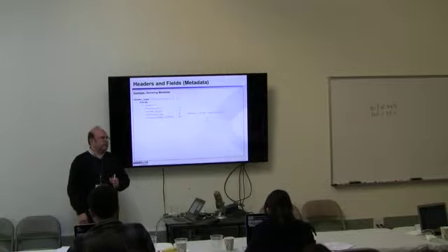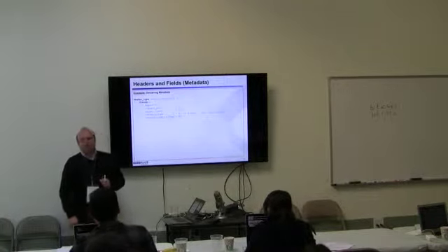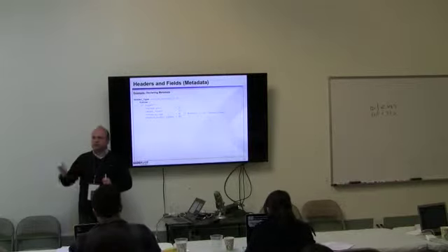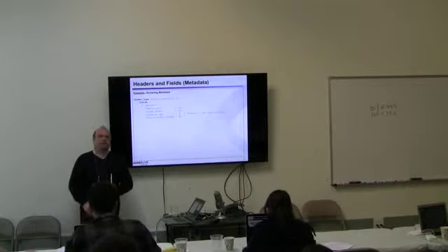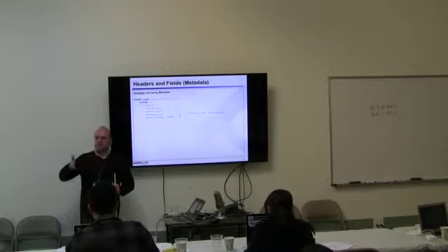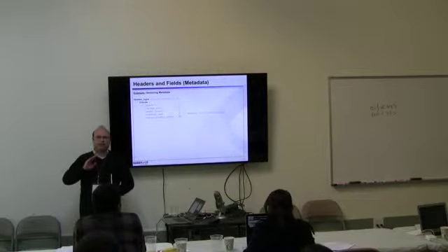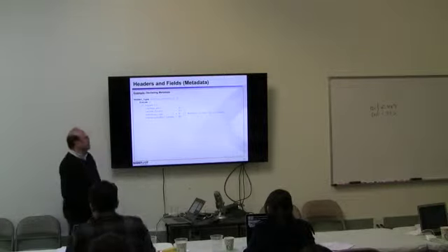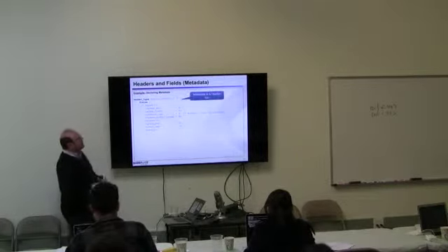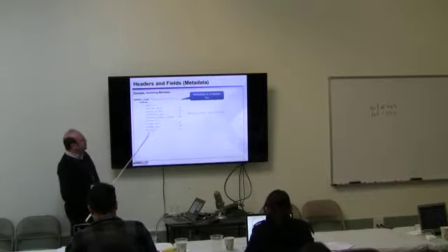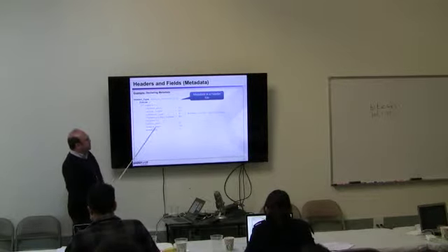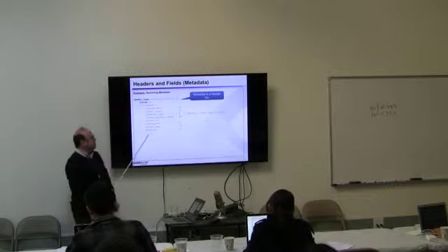Have you ever heard about protocols like 1588, for example? There are protocols which allow switches to synchronize time between them very easily, and that is based on the measurement of the delay. So the moment the packet comes in, usually in the MAC, sometimes in the PHY, it's timestamped. And there are some outputs, like the egress spec and the QID.